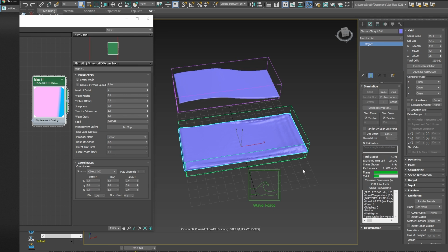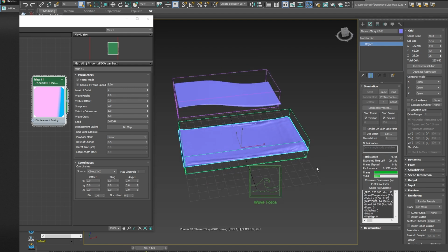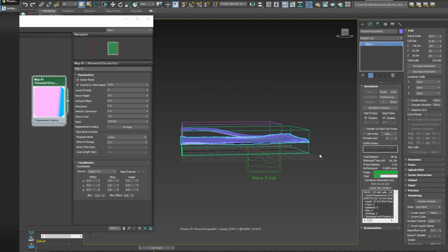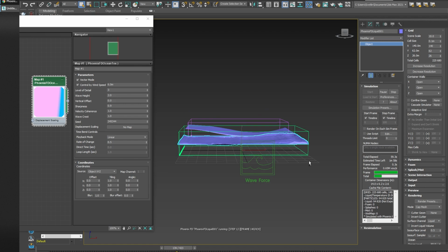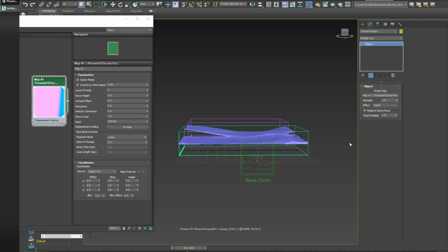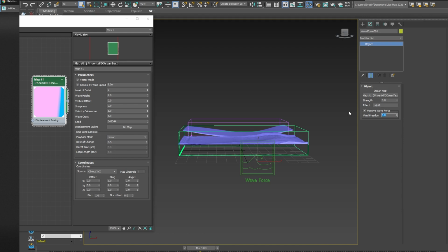And now you can see that the simulator that we currently have kind of struggles to create that wave. So now you can see that here the ideal ocean wave is starting to go up, but our simulator finds it hard to follow. So one reason for this is because our fluid freedom is set to 1. So if I zero this, let me stop the simulation, dial this down to 0 and start again.